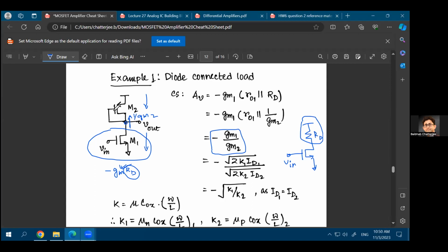If you have taken a devices class, you know what polysilicon means. It's just amorphous silicon that can be used at the gate of the transistor, and that works somewhat like a metal. It's much more conductive than a metal. And when you have conductance, 1 upon conductance becomes your resistance. So using amorphous silicon or polysilicon, you can create these resistances on chip as well.